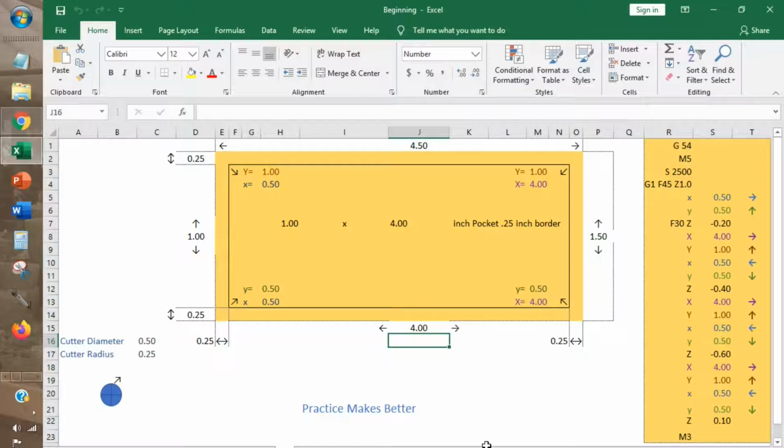I always make an error cut when running G-code for the first time. For this project, I raised my cutter about an inch above the top of my workpiece, then set Z-axis to 0. Once I am satisfied that the program is working properly, I lower my cutter somewhere in the pocket until it kisses the top surface of the workpiece. Then I reset the Z-axis to 0.